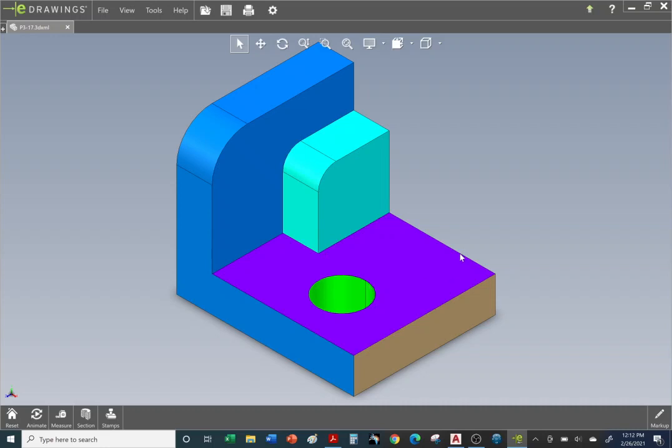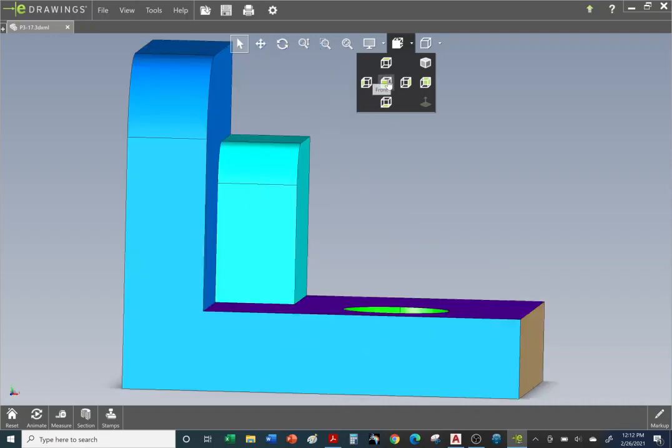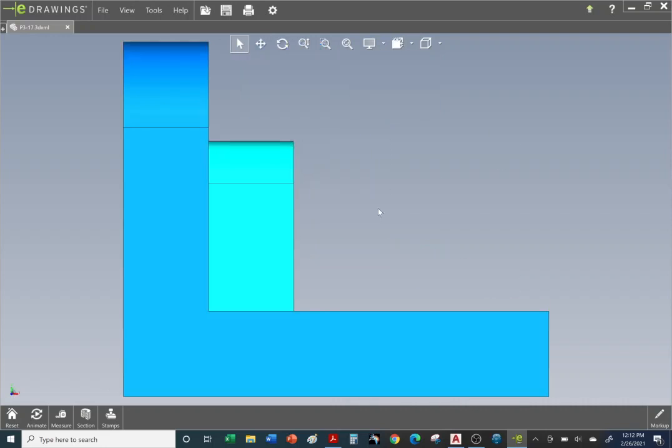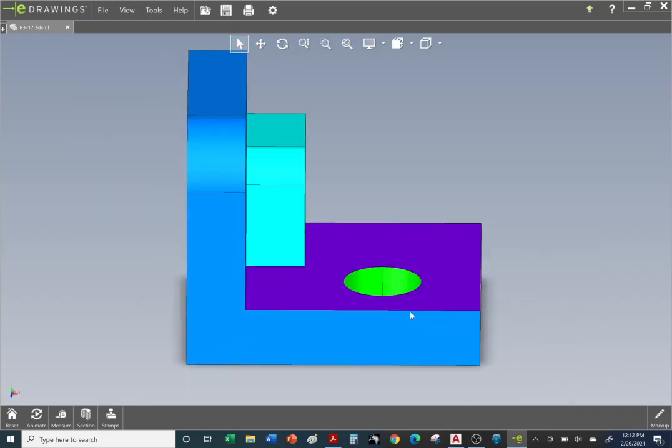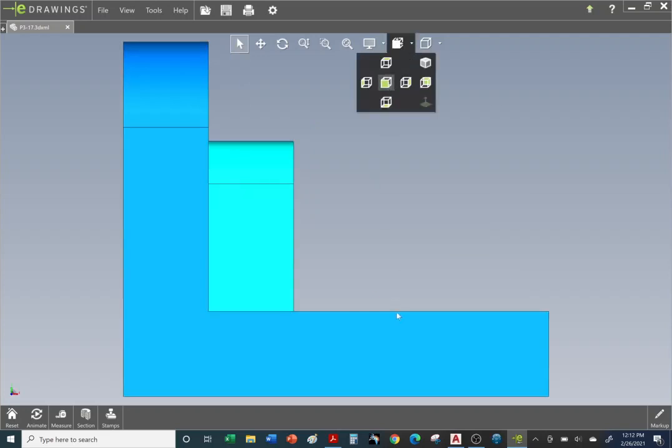All right, so let's go ahead and take a look at our front view. Okay, so here's our front view. Let's go ahead and draw these object lines, and keep in mind any hidden lines also. So we don't see the hole if we're standing in front of the building. Imagine this is a 4-story tall building. Let's go back to front view. So obviously we cannot see that green hole, that circular hole. So we'll take care of that with hidden lines and a center line.